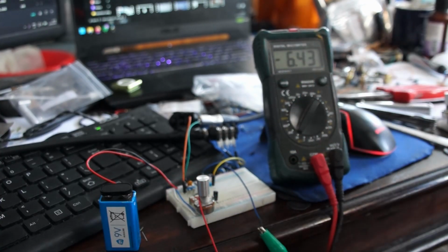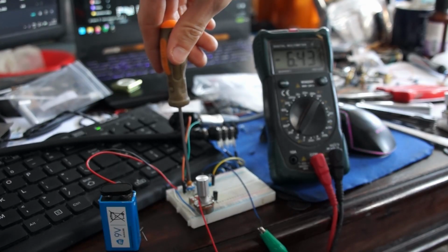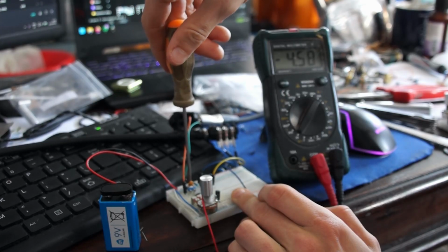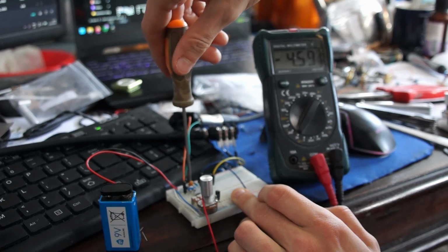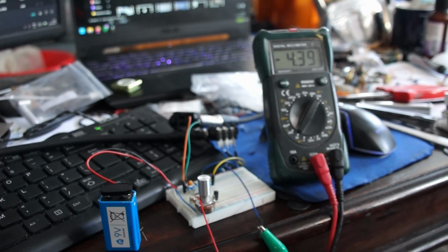I put the gain control on this thing here because we want to use that, but this trim pot we're not going to use, we're only going to use it to bias it. We're looking for 4.27 volts. I did not give myself the luxury of adding the extra resistor to make the biasing easier, so it's very sensitive. That's close enough for me.